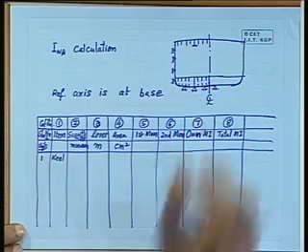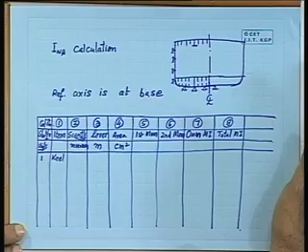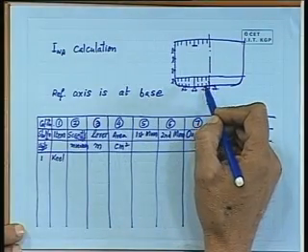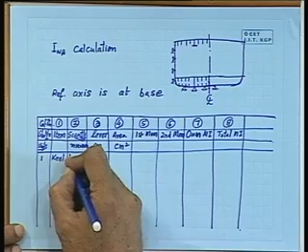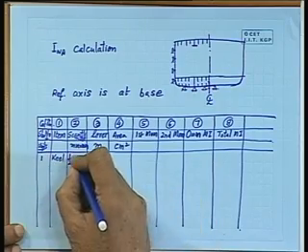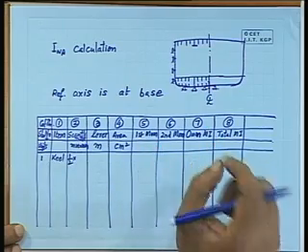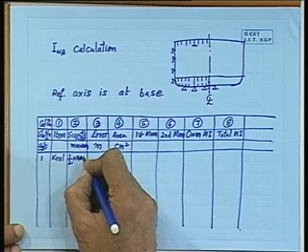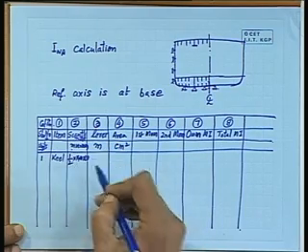Now keel plate is one single plate. We are considering only half the section. The other half is mirror image of it. So we do half the calculation, multiply it by 2, we get for the entire section. Now keel, center girder, etc. may create some trouble, and therefore one has to be very careful and put that half right in the beginning and say that the dimension is maybe that the keel plate width is 1400 millimeter, thickness is 20 millimeter. So I write 1400 by 20. I have already said millimeter by millimeter. So I give 1400 millimeter by 20 millimeter.